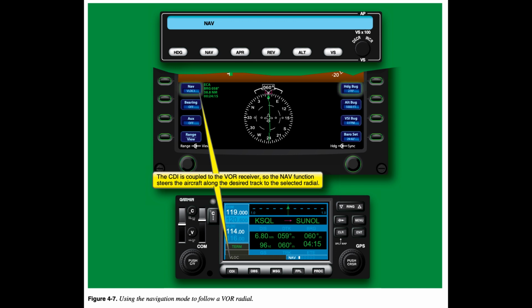Depending on the FMS, the highly automated flight that results when the navigation mode is used to follow a published route from the database uses a different skill set from using the navigation mode to track discretely tuned VOR radials. Learning how to select pre-programmed routes from the database of airways can be challenging. Programming or tuning discrete VORs en route in turbulent conditions presents different challenges. Either skill set can result in a greater sharing of duties between pilot and technology and an increase in safety.